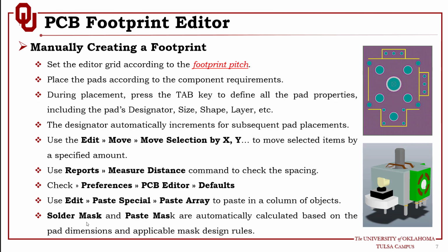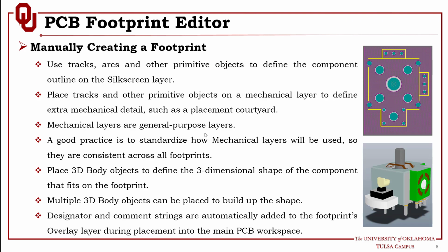So finally, solder mask and solder paste mask are automatically calculated based on the pad dimension and applicable mask design rules. Altium Designer will calculate these for you based on the IPC standard and create these as well. There are other notes. It's better to go through these notes before we start creating the footprint.